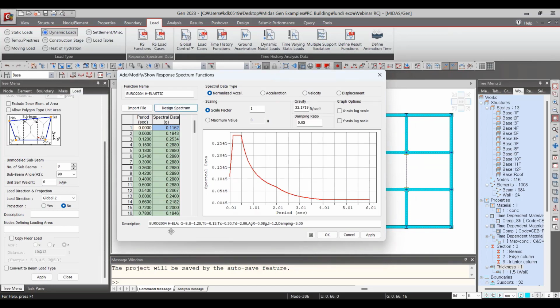The software can give directly the parameter we need for the seismic load in the spectrum. I showed you previously in the PPT file. I showed there is S point here, and then TB, TC, and TD here, the period. Those data can be generated automatically after selecting the design spectrum you're going to use.